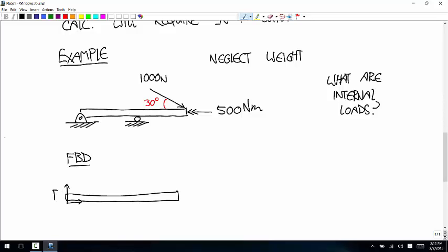A force vector, good. And then a roller. Oh, one more thing too, actually. This kind of depends on the specifics of what the joints are like, but this pin joint isn't going to let this thing barrel roll, right? So this is also going to produce torque along the long axis of the beam. We're going to assume that this roller doesn't, although it depends a little bit on what that joint really looks like. So there's a force RA here and a torque, I'll call it TA here.